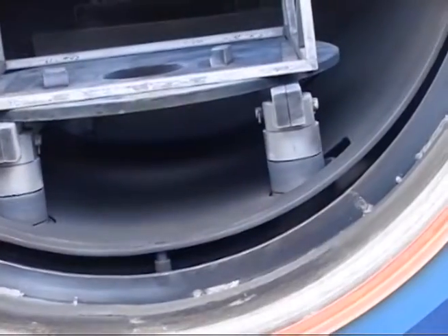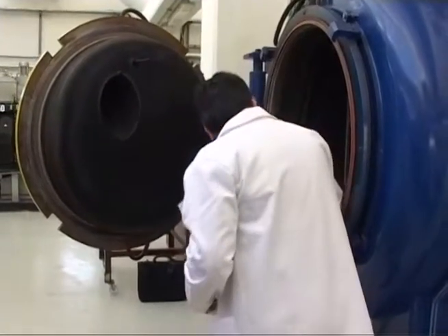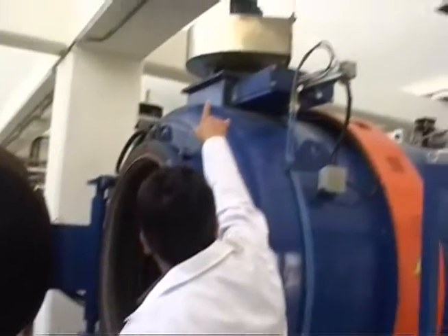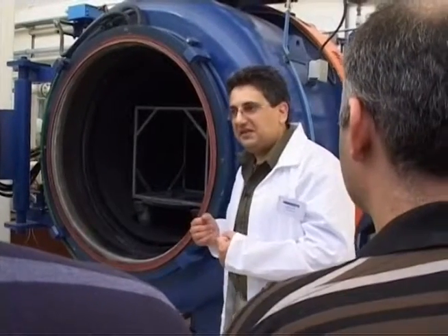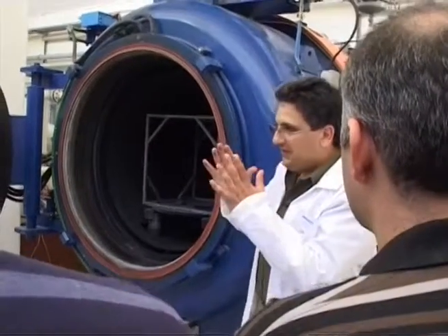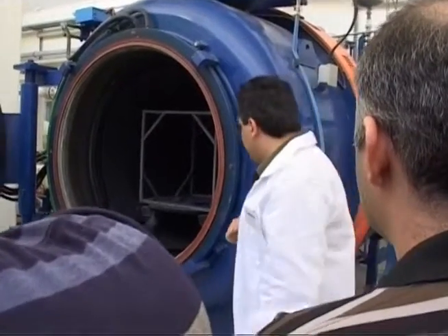This part of the chamber is allowed to heat up to the process temperature, while in the space in between there is cold air which is forced by the upper ventilator. This configuration allows more flexible control of the temperature inside the furnace, not just by controlling the energy input by the resistors, but also by cooling the furnace, thereby reducing the operating window or the control window of the temperature.